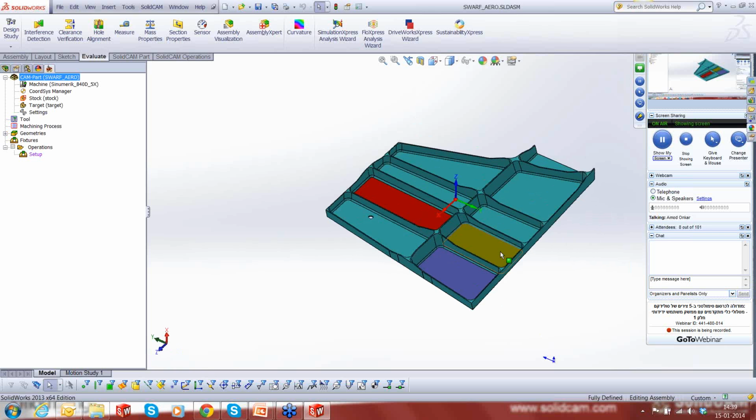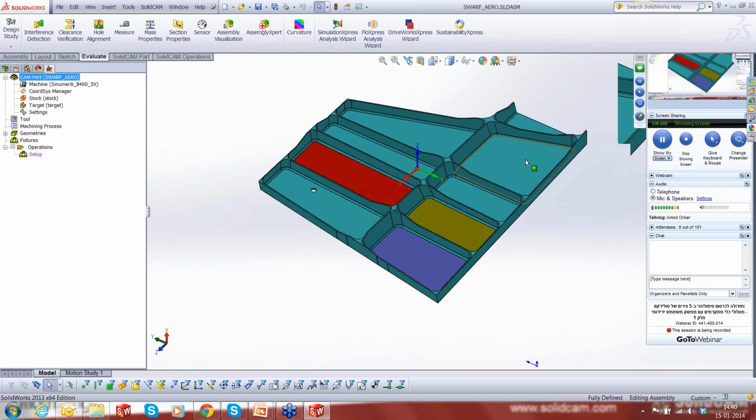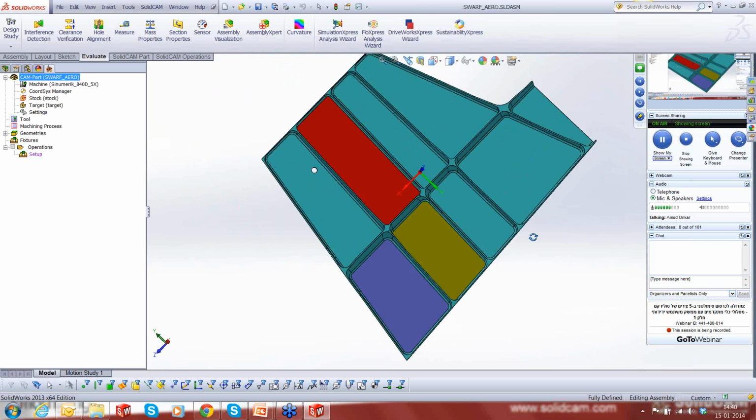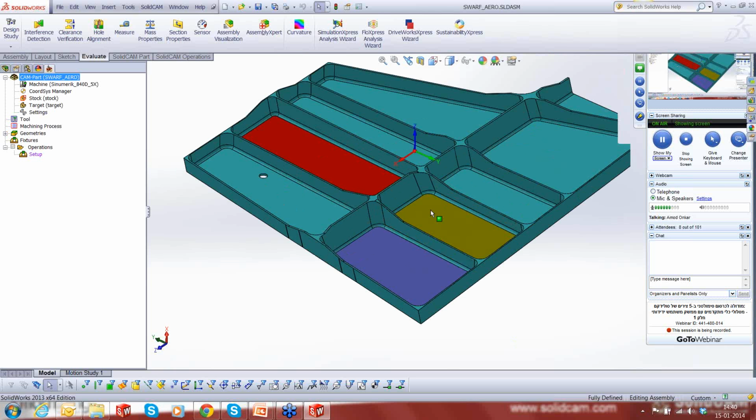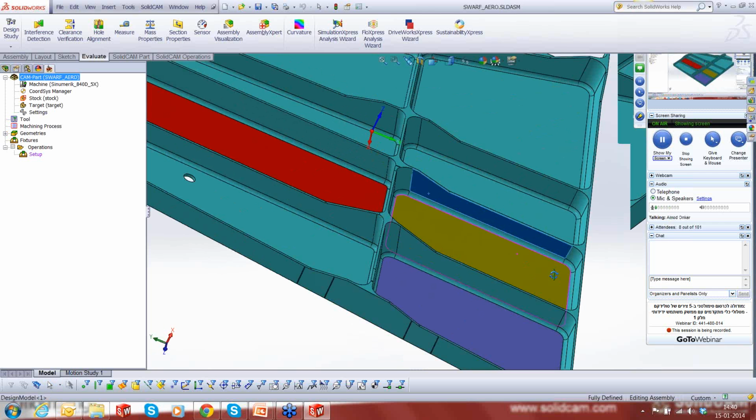One is a pretty automatic way where it generates results very quickly, and in a similar kind of pocket where we are not able to generate it automatically, how we can further tune up the entire tool path using some new tilting mechanisms available in swarfing to generate a very effective tool path. All right, like you can see, it's just a portion of a frame part, and we are going to swarf these faces, the ones that I'm marking at the moment.